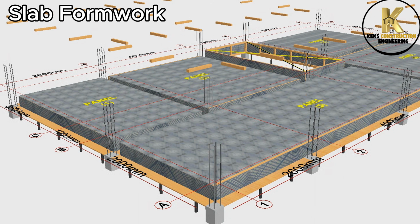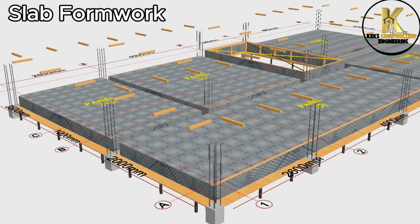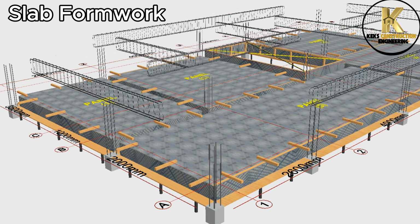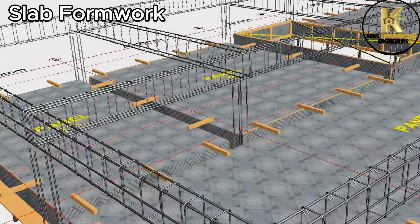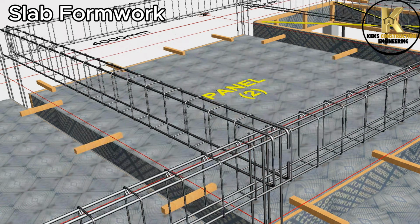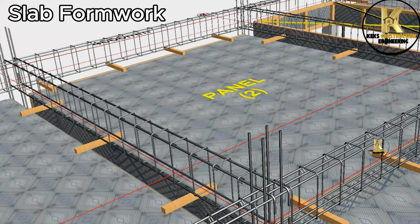These short woods are placed temporarily to stand the beam reinforcement so that it can be fixed, aligned, and properly inspected before lowering the reinforcement into the formwork. With this method, you can easily make corrections on the reinforcement without wasting time and extra money.